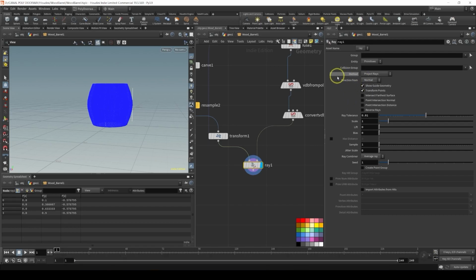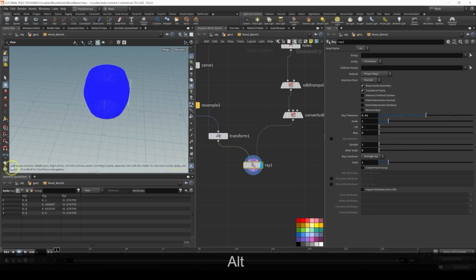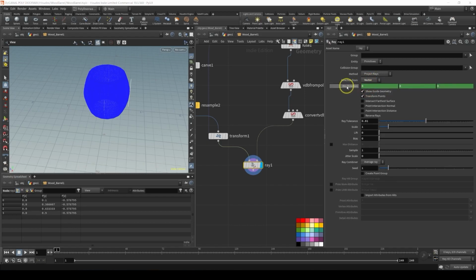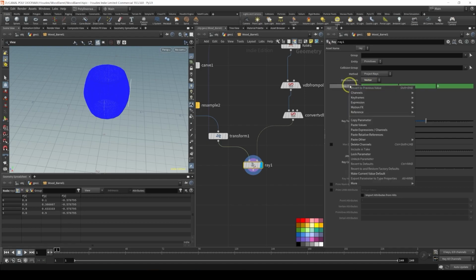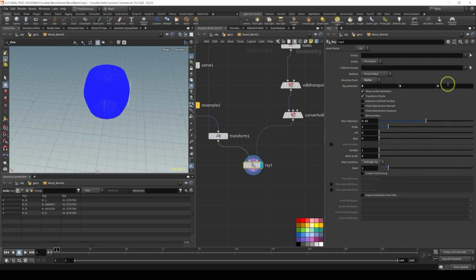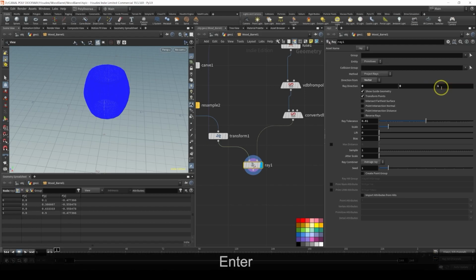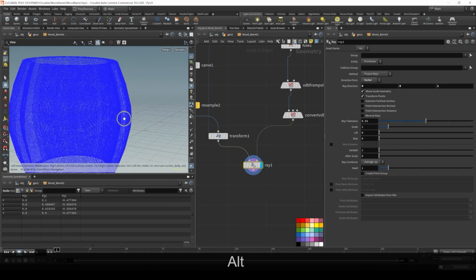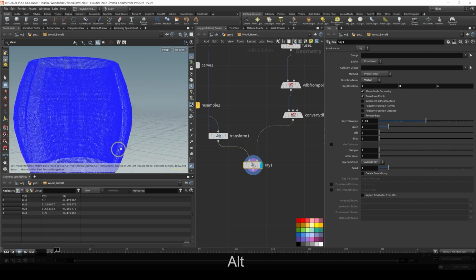We're gonna change the direction to give a vector that is a reference to the Z direction. So let's change it to vector. Delete the values of the ray direction property. So right click, delete channels. And here in the Z direction, we're gonna set it to 1. Now our line is matching the edge of the barrel.